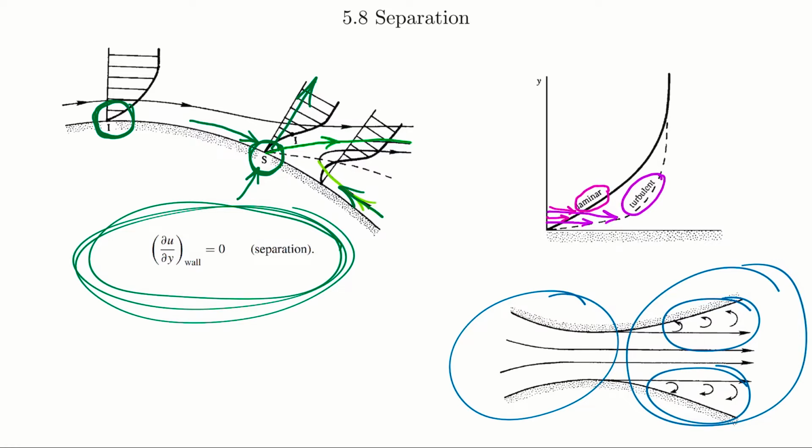Because we have flow in the opposing direction. And also one final problem is we can't apply our potential theory to find the pressure distribution in the separated region, because our effective boundary of our irrotational flow is no longer just a solid surface, but some unknown shape that's encompassing part of the body plus the separated zone itself. Okay, so we'd no longer be able to calculate the pressure distribution.